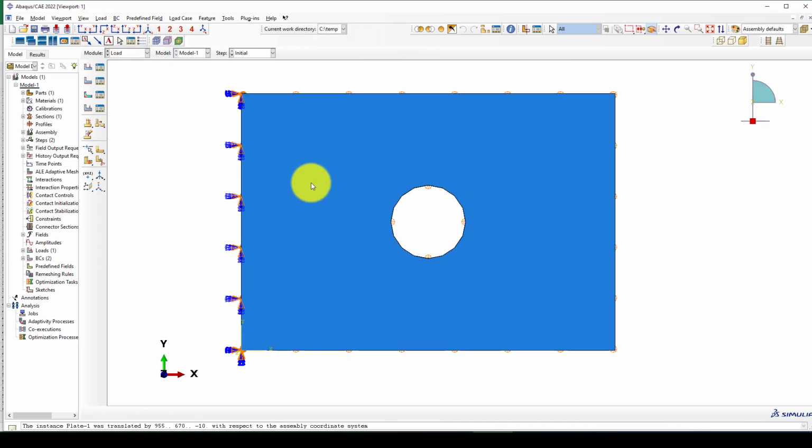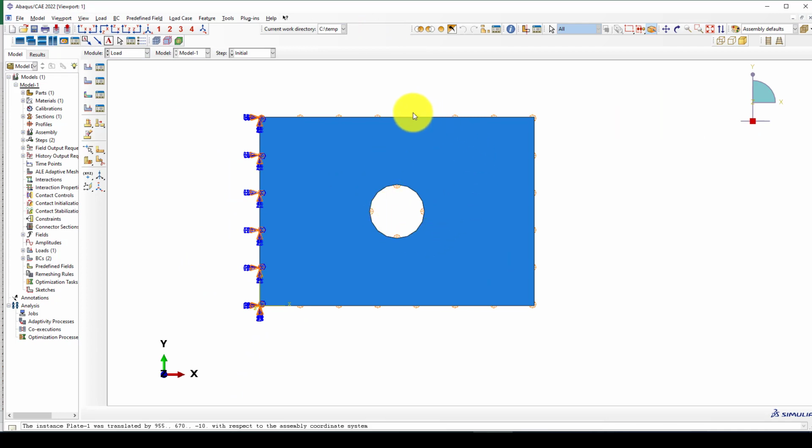This is very important, otherwise the structure is not stable, we cannot get a good result. So in practice we don't have such an element to load like this, but instead we have something like a box or some sort of support in the lateral direction.